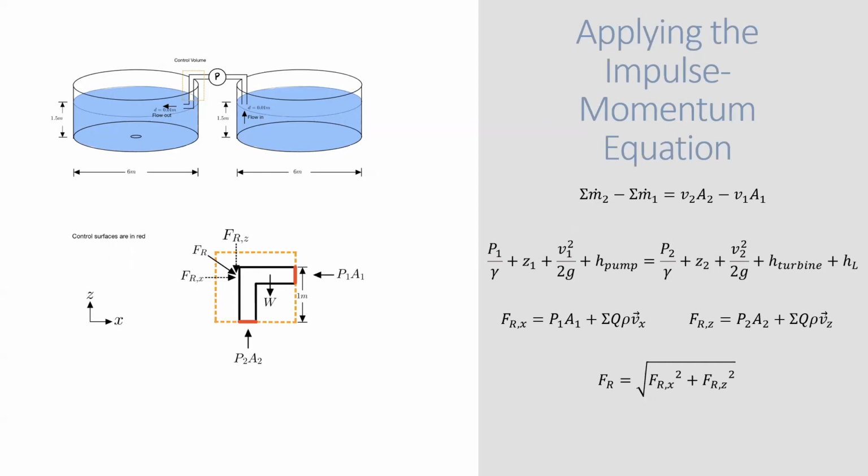As for ways the system could be better understood or optimized through this kind of modeling, say a specific velocity is required for the fish to maintain a healthy environment. This type of modeling can be used to determine the required pipe diameters, horsepower for the pumps, pipe heights, etc., to make sure such a velocity can be reached efficiently.